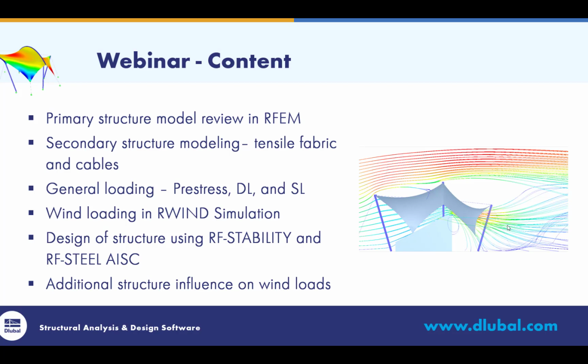From here, we want to get into the general loading. This includes the pre-stress forces that are necessary for the form finding process, but also a couple of simple load cases such as dead load and snow load. Then we'll move on to wind loading, and for this we want to utilize one of our newer programs, RWIND Simulation. This is a CFD wind analysis program, which stands for Computational Fluid Dynamics.